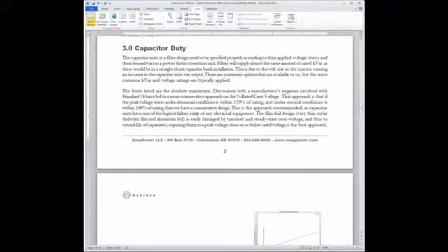Now, it may not be. It may be phased off a bit, okay? But we really don't want to play that game when we're rating equipment. So what we want to do is make sure that when the peak voltage of the fifth harmonic appears and adds linearly with the peak voltage of our fundamental waveform, we have taken that into consideration for the voltage stress going to be put on the capacitor.